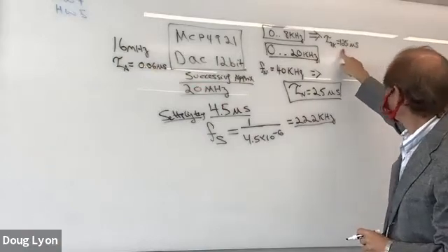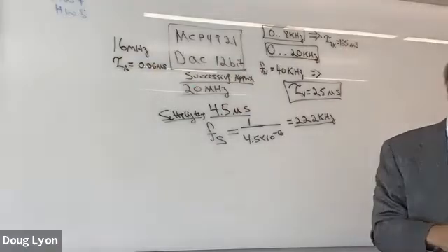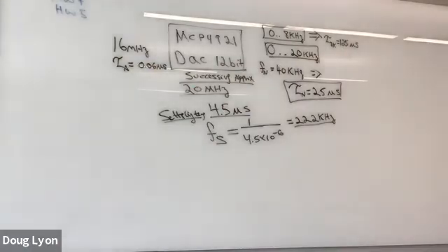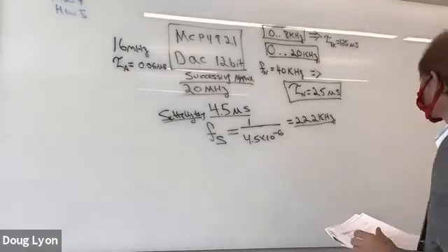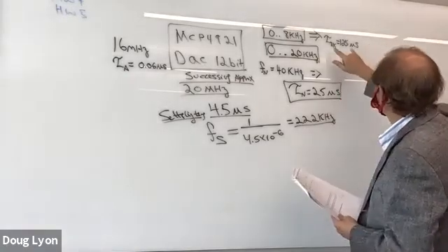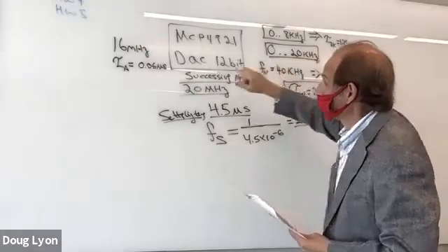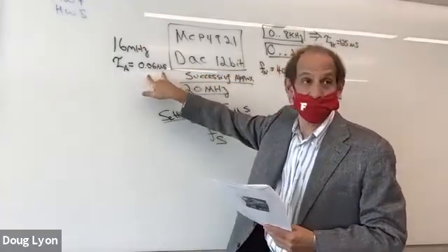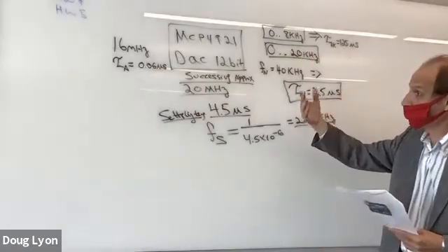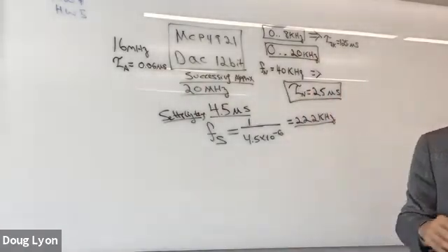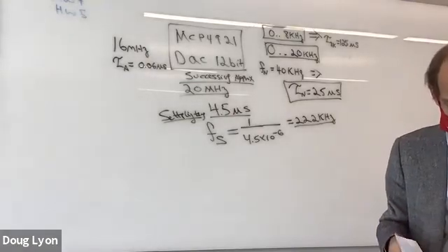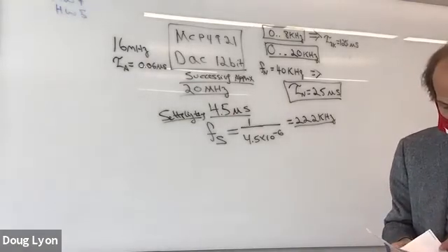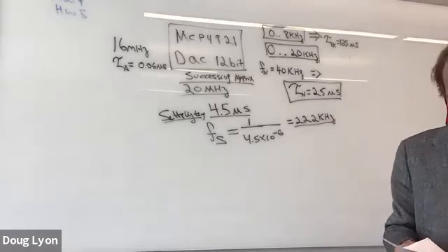And I like that because I need to actually take the data and process it. And I need those extra cycles to do the processing in between samples because I can't store a lot of data this way because Arduino just doesn't have that much RAM. So if I'm going to do signal processing, I need to have a reasonable ratio of sample rate to processing rate. And that's a pretty good ratio because what that tells me is I have spare cycles to work on the sample after I've sampled it. Because if I don't have that, then I can't do very much in the way of signal processing.